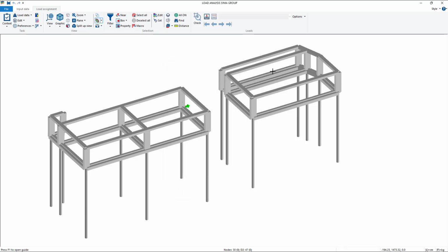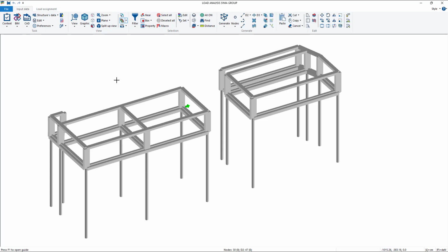And we can close this. Okay, I just forgot something, because now I wanted to show you how to insert pressure load for the soil. So ground pressure, either in static and dynamic conditions, so either on self-weight or under seismic activity. In order to do that, we need to have some wall elements or panel elements that are needed to distribute the pressure load. So we go back on input data.